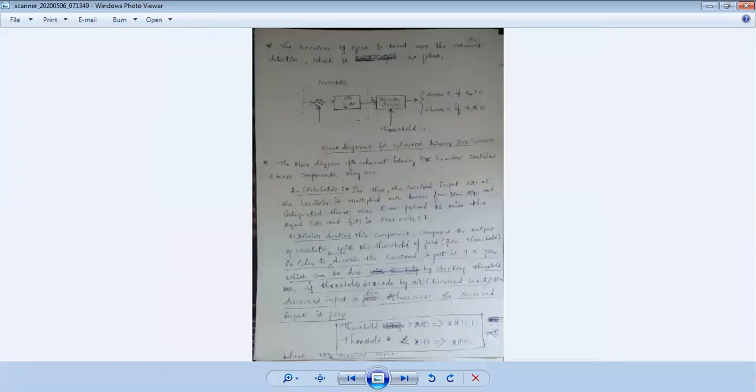So I hope this is exactly the block diagram of BPSK coherent detection. At this point, you have to mention why it is coherent and not non-coherent. One more important point: as soon as the signal comes, it is multiplied by the basis function and integrated over 0 to T to give x1, and the decision is taken with the threshold voltage. Okay.